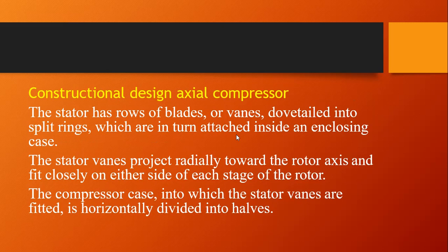Construction or design of an axial compressor. The stator has rows of blades or vanes dovetailed into split rings, which are in turn attached inside an enclosing case. The stator vanes project radially toward the rotor axis and fit closely on either side of each stage of the rotor. We're looking at the construction design.